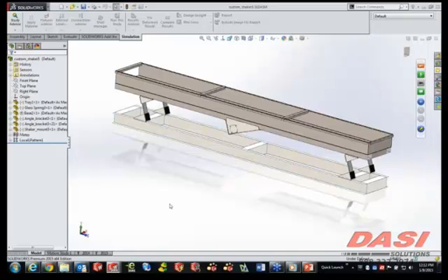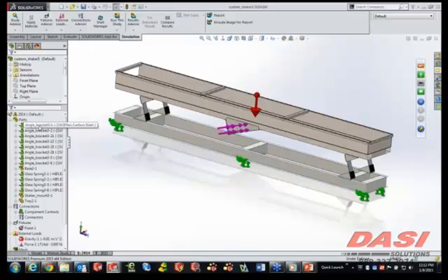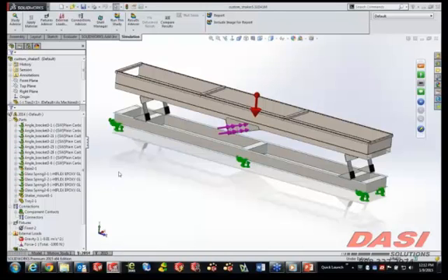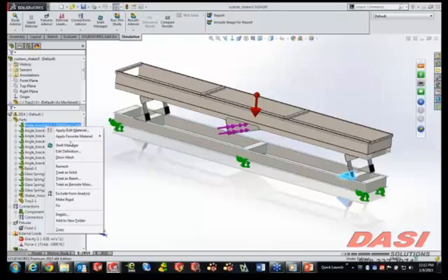And through the normal interface up to 2014, we'd always go ahead and create a study, and then with that study, we'd go ahead and define the thickness of each of the pieces of geometry. And in order to see the thicknesses, you'd have to edit each body within the parts tree. Very difficult, especially to change things, especially when you're changing several things into a new value. So what we've created is this brand new thing called the Shell Manager.